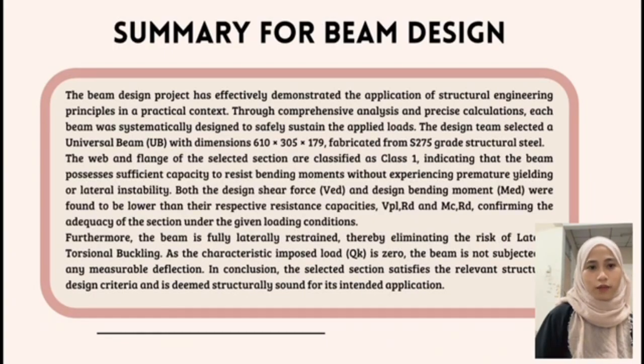Furthermore, the beam is fully laterally restrained, thereby eliminating the risk of lateral torsional buckling. As the characteristic imposed load Qk is zero, the beam is not subjected to any measurable deflection. In conclusion, the selected section satisfies the relevant structural design criteria and is structurally sound for its intended application.